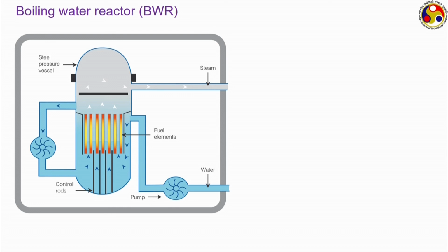A boiling water reactor is the counterpart, where again we have a big pressure vessel just like this, but inside we do not have any pressurizer kind of component here which can control the pressure, and therefore, once the heat is supplied, the liquid temperature can increase up to the saturation temperature level and may start boiling. So, in case of a boiling water reactor, the liquid enters the tank from somewhere here, like this.